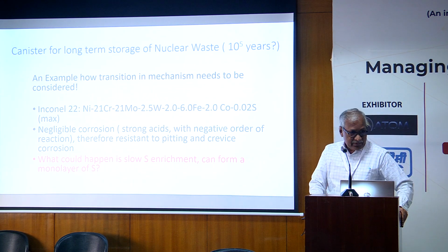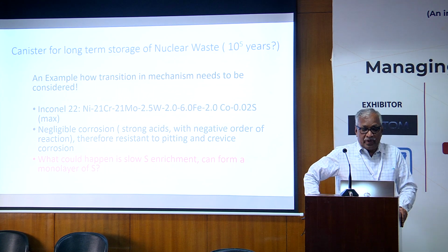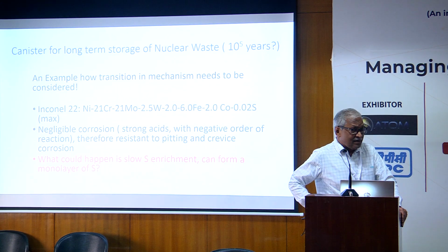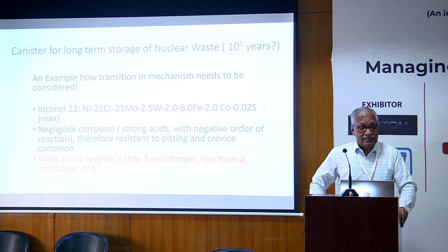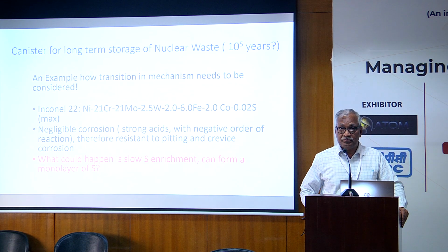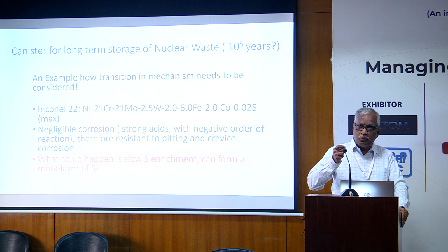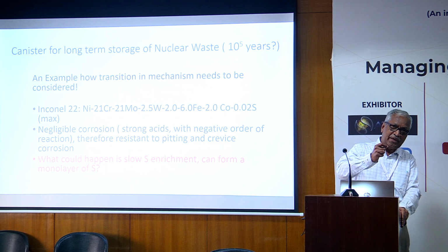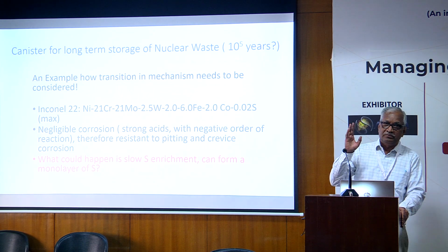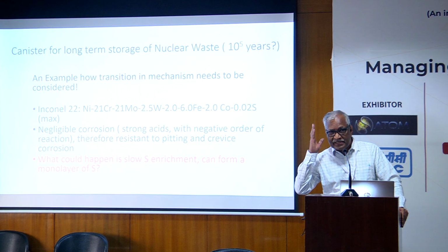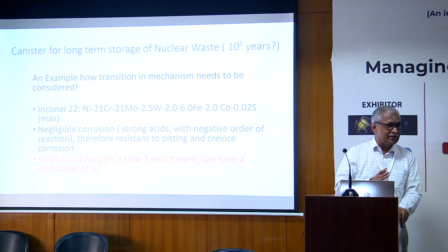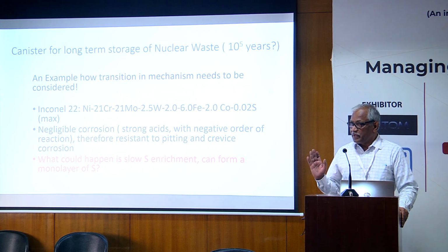We talk about canisters for storage of nuclear waste. They have to last for 10,000 years. People tested this Inconel 22, the best alloy. You put it in 5 molar hydrochloric acid and it doesn't corrode. I mean, no pitting, no crevice corrosion. If the alloy is resistant against pitting corrosion and crevice corrosion, I don't think there's any problem at all.